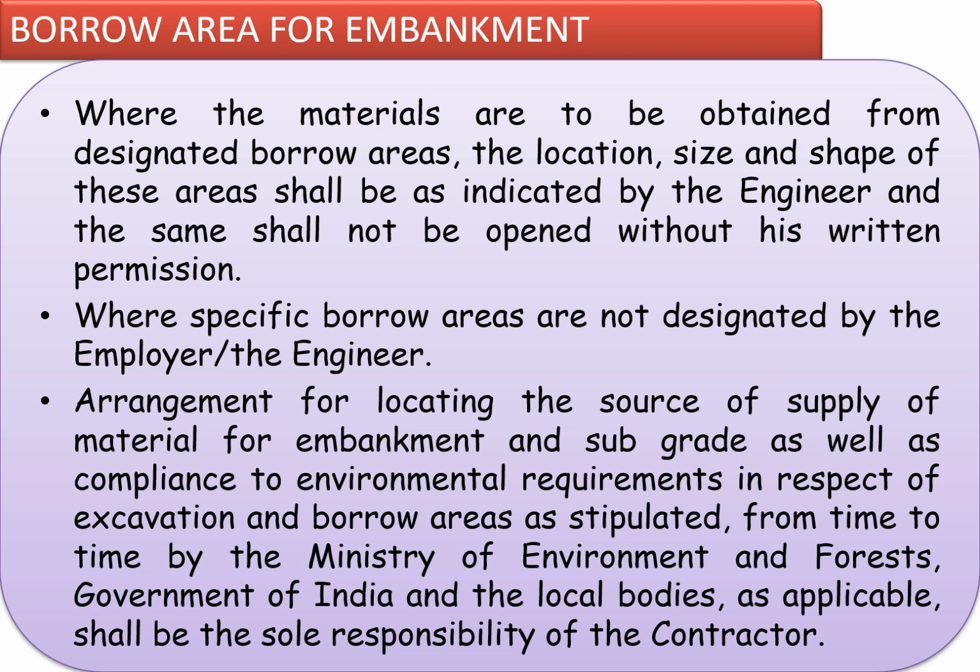The other part which we discuss normally is the borrow area for embankment materials. When the cut material is not suitable or not sufficient to complete the construction of road work by filling, we look for new material, which is basically borrowed material from nearby places. Where the materials are to be obtained from designated borrow areas, we specify them.